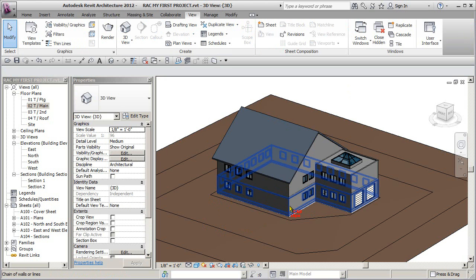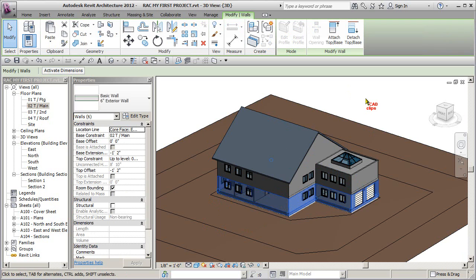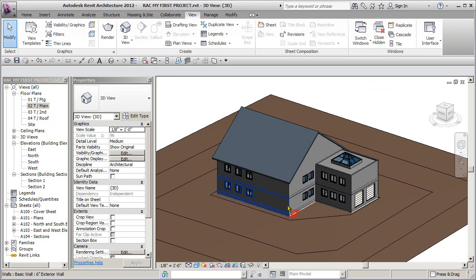Watch, we'll do another one here. I'll go hover, Tab, select. Now my hands are off the mouse, off the keyboard, it's been selected. Now my hand's back on the mouse, over to the keyboard. Now I want to add these guys in. So what I'm going to do is tab once, hover, Tab, then hold my Control button in and click. I had to hold my Control button in because if I didn't, it would have deselected the first selection. That rule still applies. If you don't use the Control button and you make a new selection, it will cancel the first selection.